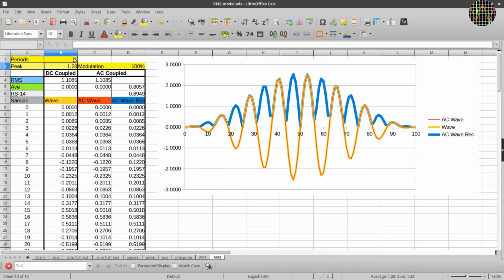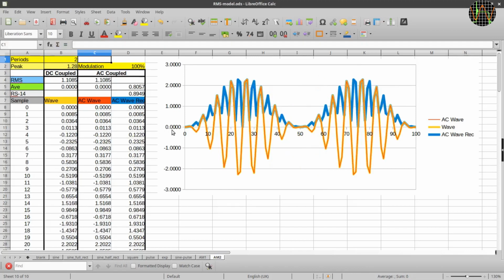If I set the period to 2, the shape of the yellow trace makes it very clear that in AM the modulation value basically turns the volume knob of the carrier amplitude up and down. You can see the shape of the 50 Hz modulating sine wave in the outline of the yellow wave. The 400 Hz carrier modulated by 50 Hz is implemented as the ratio 8:1 in the formula.